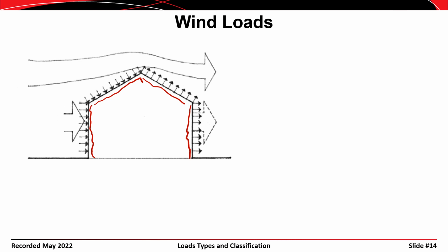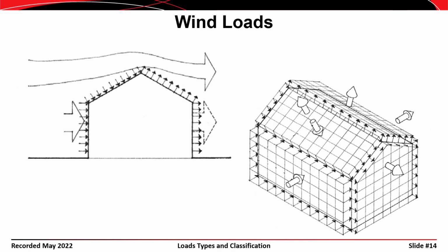Depending on the angle of that slope, as the angle goes from 0, a flat roof, up to something like a 45-degree angle, then the forces on the windward slope portion go from a negative value to a positive value. And you can see that in this image here, where this is drawn in 3 dimensions. And you can see that on the windward part of the sloped roof, that force could either be positive or negative. It could cause a pressure or a suction at that point.